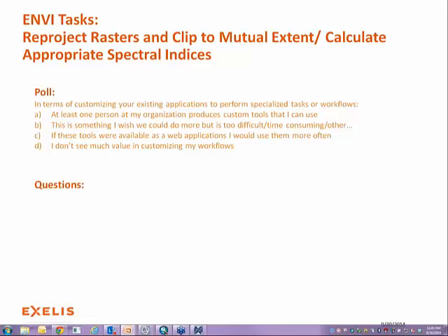It's fine for those geomorphological products that you need. The low resolution LiDAR is fine. If you're doing feature extraction, where you want to pull out buildings or trees or power infrastructure or anything like that, you probably need a higher point density. There are some other sources for that, usually private vendors or something of that nature.